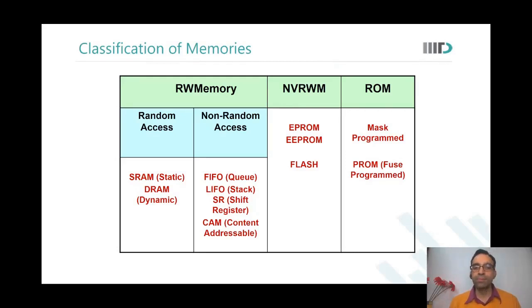Thank you. Okay, so content addressable memories. Any questions about that? In this, we are trying to go the reverse way, from the content to the address. But for the content matching also, there would be some kind of reading from a particular location that matches. Wouldn't there be? Yeah, so in a typical SRAM, you will have to read and compare, and then say whether it's a match or not. If it's a 100 word RAM, you will have to do 100 cycles to do even one comparison. Am I right?